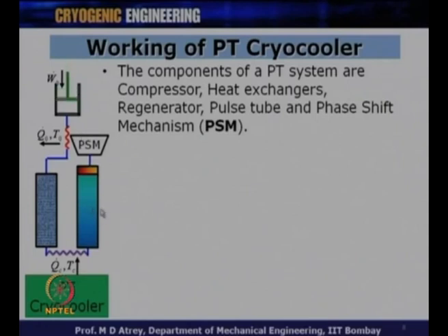So, earlier we had a displacer, and as I said, every time the displacer and the compressor have some relationship in their motion. Now, we do not have any mechanical moving component here, and therefore, whatever gas is moving at this point, I have to see that the gas moves in accordance with what I want, which would generate cooling. So, I have to ensure that the oscillations set up in this tube move in a fixed manner, in a manner which generates cooling, and this manner in which they should oscillate in this tube is basically due to the phase shift mechanism, PSM, that is what is written over here.